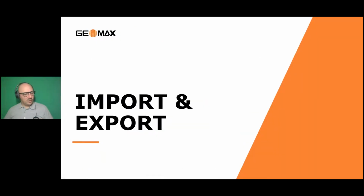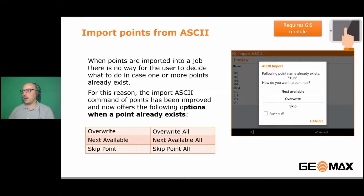Okay, we are close to the end of the news and also close to the time we planned to dedicate to this webinar. Just quickly, import points from ASCII. No, sorry, this required GIS module is wrong. So what does it mean? It means that now when you import a list of points and there is already a point with the same name in the database, you have this option. Before, the point was automatically renamed. So if you had a point 100 and you imported a point called 100, the point was called 100_2. Now you can choose: change the name, rename it, overwrite, or skip the point. So it's much more powerful to manage when you import the data.